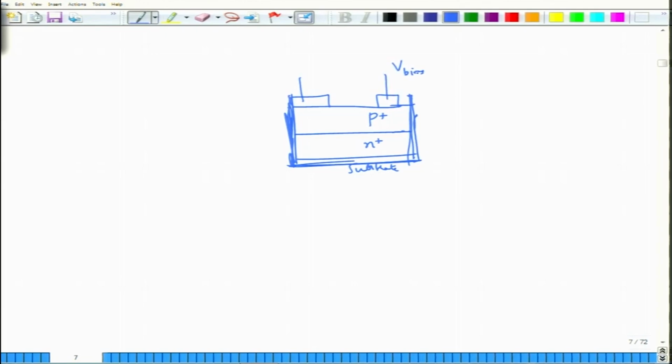Okay. So, this is how it would be, and there would be usually a small layer of anti-reflection coating, and light would come in from this side. So, you would illuminate from the top, so that the light would actually propagate through and create an electron and a hole pair. Now, this region would normally be the depletion region, and because of heavy doping on both sides, the depletion region is quite wide. Okay. The width of the depletion region is W, or we will call this Wj. J stands for the junction.